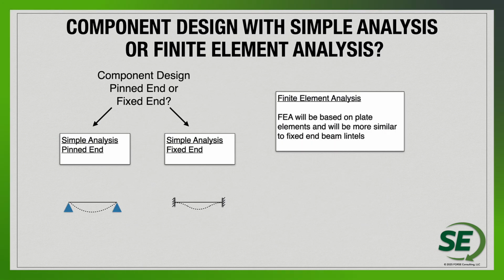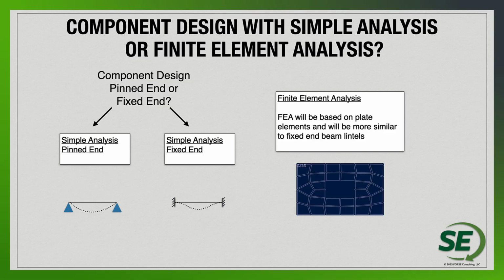Looking at and maybe considering what finite element analysis software would be able to help us with, maybe we can understand a little bit more about this. Again, the traditional way to look at a lintel would be the simple analysis, pinned end kind of approach. We know that lintels are integral with a wall on each side of it, so we also could consider that a fixed end element, and then we have finite element analysis that can help us have a better understanding for the overall design of these elements.